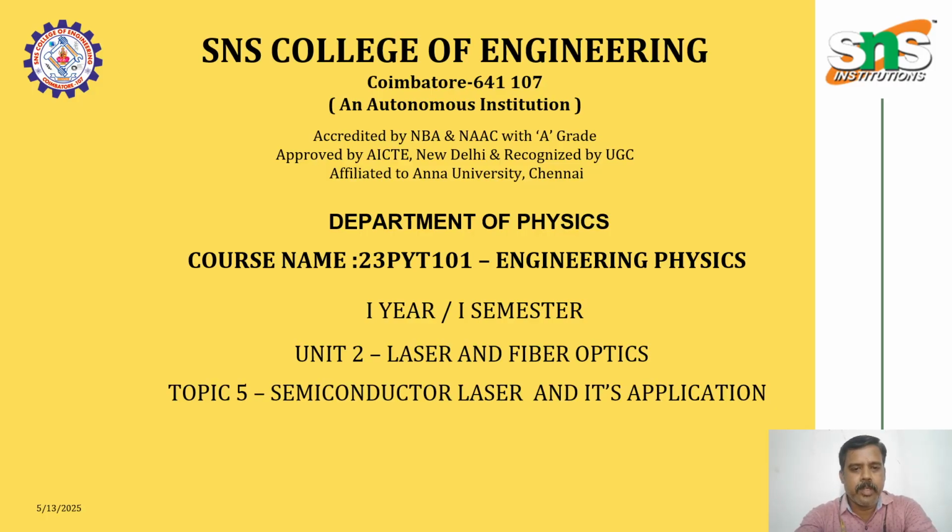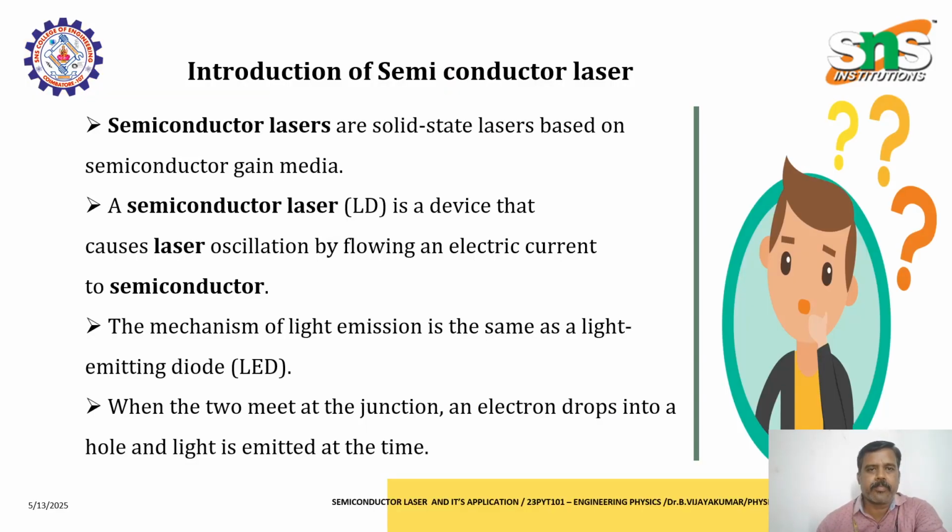Another topic to discuss from the unit of laser and fiber optics is the semiconductor laser and its application. This is a special case of solid state laser, because we already discussed the solid state laser, Nd:YAG laser. So this is another type of solid state laser. The introduction of the semiconductor laser: it becomes solid in nature based on semiconductor gain media.